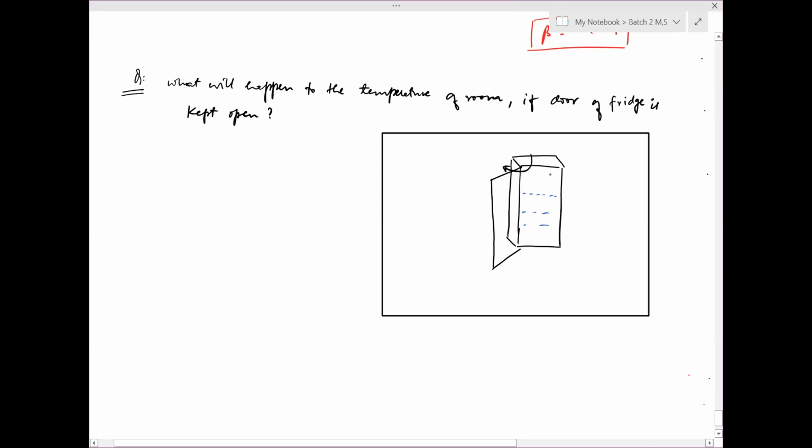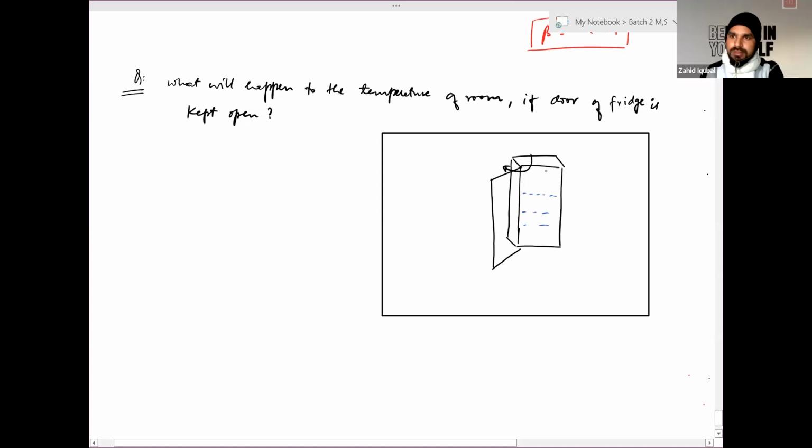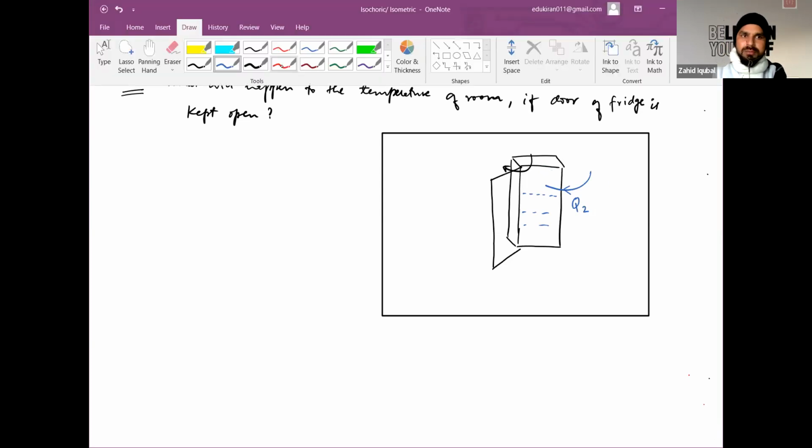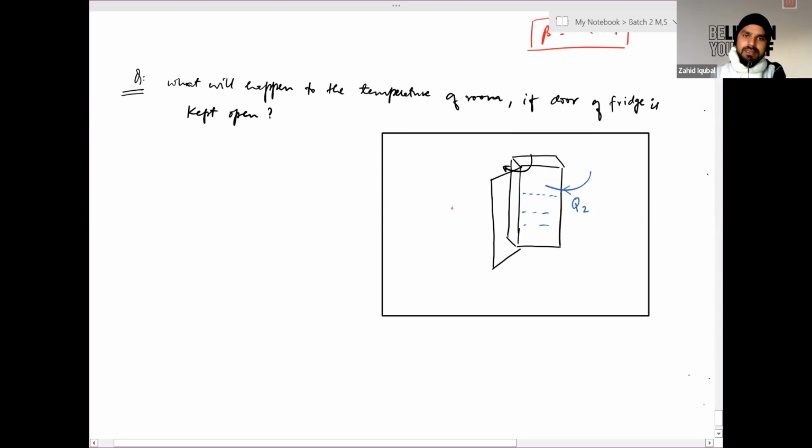Yes, sir. So the fridge has to absorb heat from that cabin, which has now become the entire room. So it absorbs a small amount of heat from this entire room, and by adding the work of the compressor, it ejects a large amount of heat into the same room. So on each cycle, the work done by the compressor increases the temperature of this entire system or room. Hence, the temperature of the room gradually increases. Shravya, is it clear?